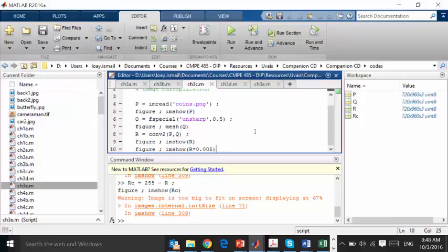Right? What can be done with convolution in the spatial domain or in the time domain can be done by simple multiplication in the frequency domain, and vice versa. Whatever can be done using convolution in the frequency domain can be done using multiplication in the time domain or spatial domain. Okay? So since I want to apply my filter in the spatial domain, in this case I will apply the convolution. But in 2 dimensions. I have X and Y. I have, for example, the rows and I have the columns. Right?